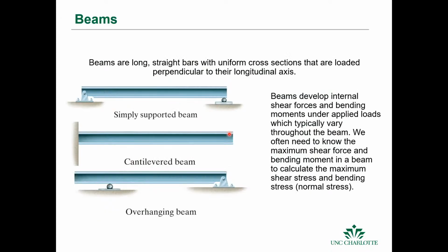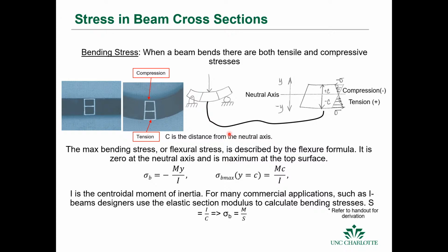All right, so let's talk about beams. So far we've talked about shear and beams, and we've talked about simple shear, and now we want to talk about stresses developed in cross sections of beams as well. So when a beam is bent, if you have a symmetric beam, the top half is in compression, the bottom half is in tension, as shown here.